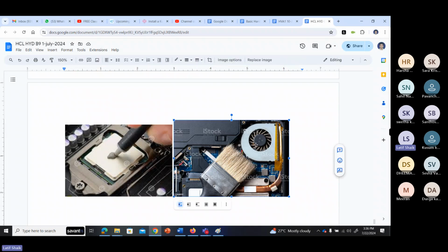This side is laptop. On the fan also, sometimes a lot of dust is there. So you have to clean it with an earbud or something similar. If it is not sticking to your earbud, then use some isopropyl alcohol. Rubbing alcohol is always better. Okay, don't use sprays. You can use an air compressor spray, which can also blow out this